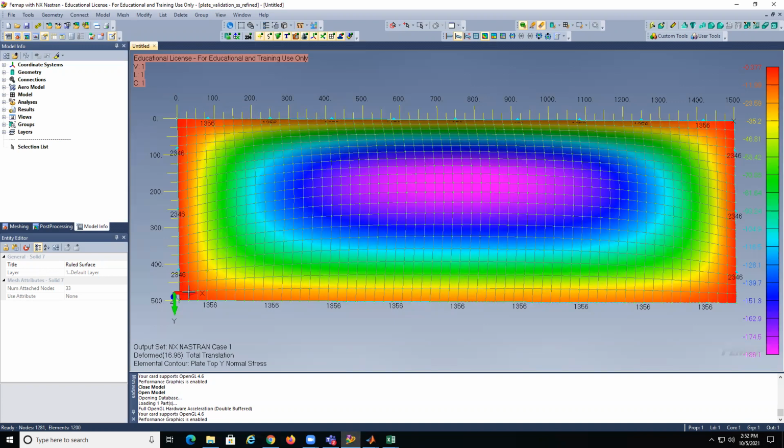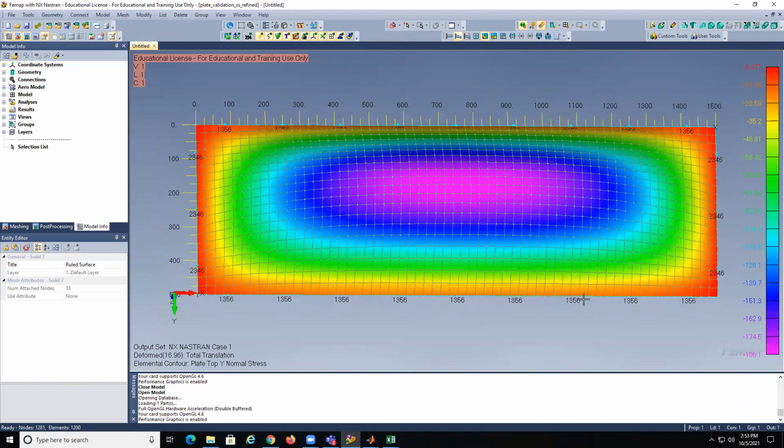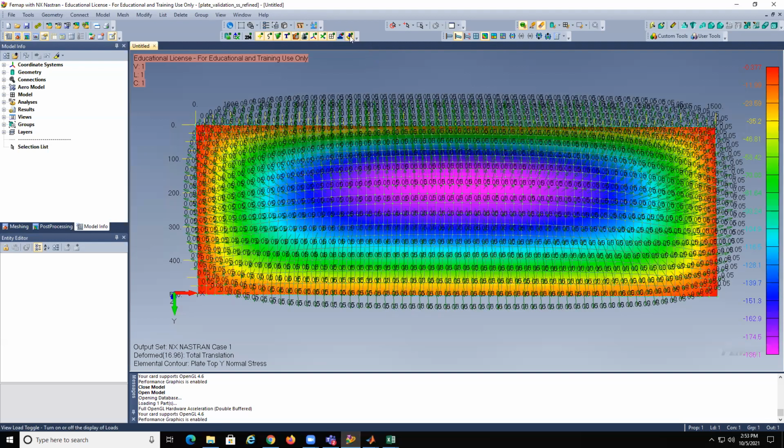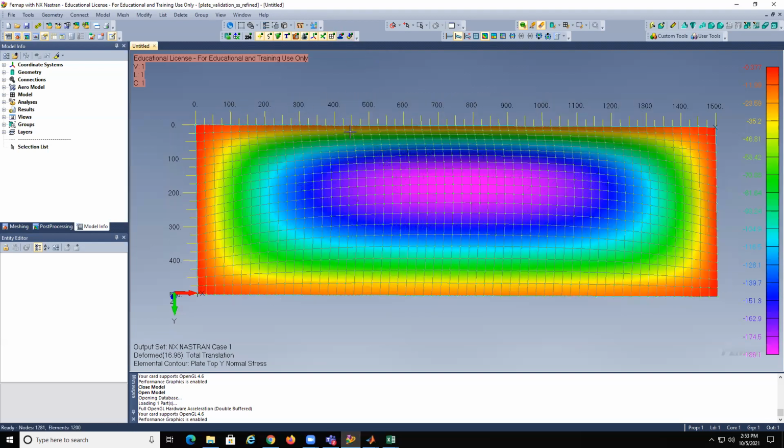This is a plate that you see is 15. This is the boundary condition, but it is 1500 millimeters by 500 millimeters. I just did a surface. You create the mesh. I think each one is 25 or 50 millimeters. And I'm just going to open here very quick.